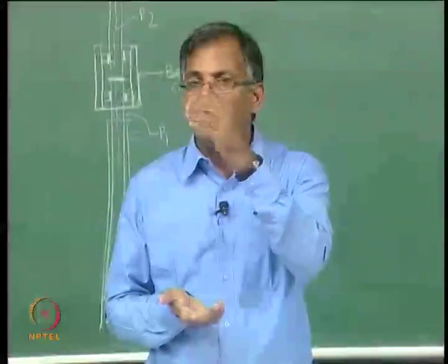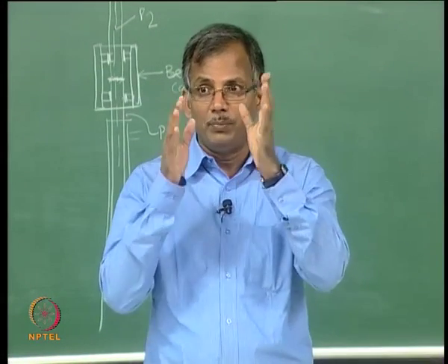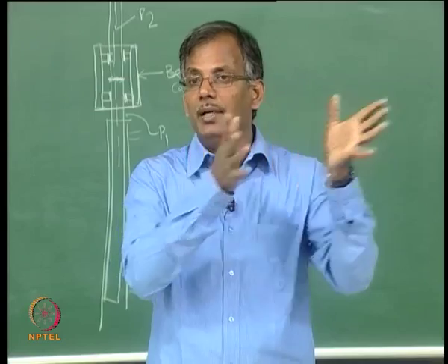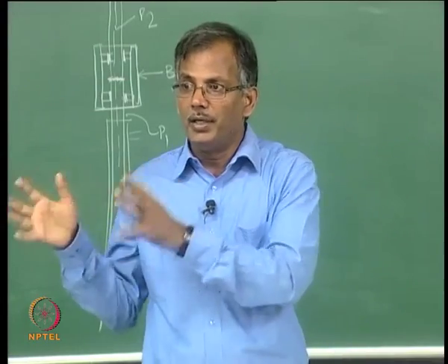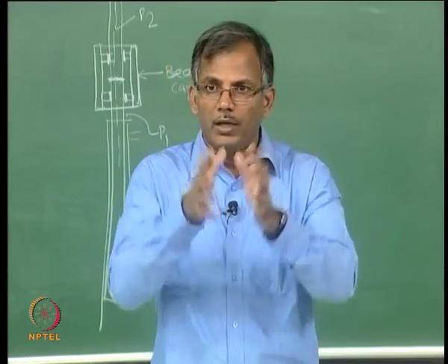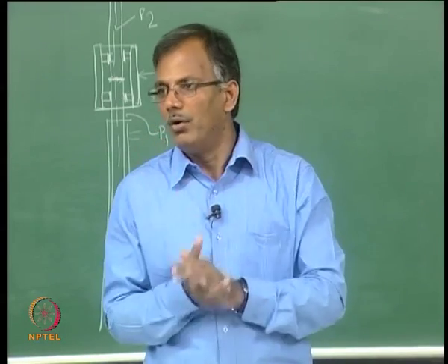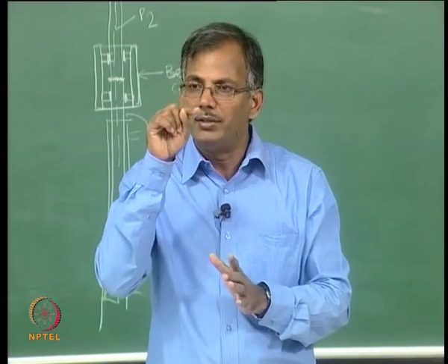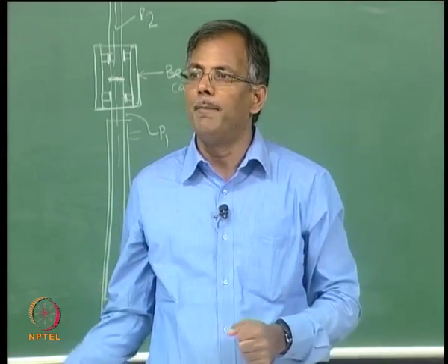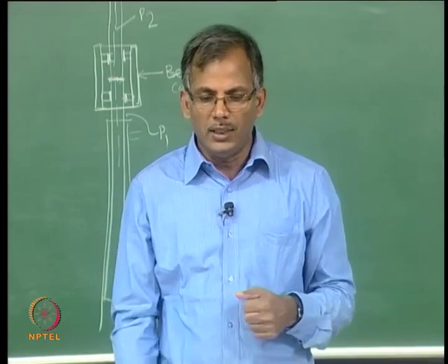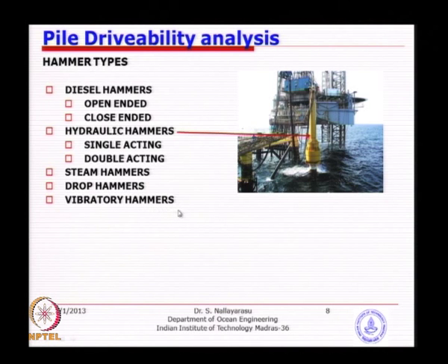As I mentioned earlier, in some cases if you are unable to place the hammer because of its weight, bending stresses are going to be larger, then you bring in a vibratory hammer, put it on top and just vibrate, and the pile might actually go slowly down until such length that you can remove this and place the bigger hammer. So, that is the idea behind the vibratory hammer, to vibrate and see whether the pile goes down without much effort. So, these are various types.